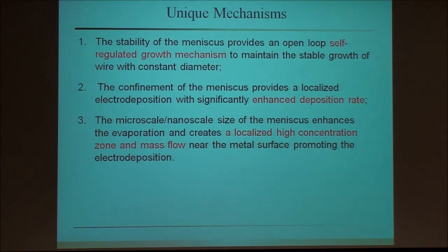Because typically when you try to deposit a small wire with small structures through physical contact, it's very difficult to control a physical gap. But once you have the meniscus there, the meniscus is stretchable. So it provides you a window of stability. And this window of stability in terms of manufacturing is very, very important. Everything has a certain kind of instability, either through mechanical vibration or other kinds of perturbations. And since we have this meniscus, it provides enough stability, and we have analysis that it provides a window of stability about half the size of your pipette.